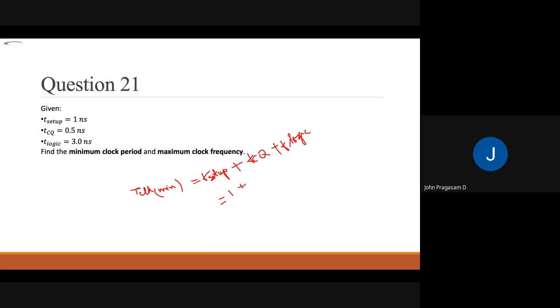In our lab we purchase some HEMT substrates, like aluminum gallium nitride. Yes, we directly purchase the HEMT substrate. Then we deposit or decorate some material, fabricate the contacts, and use it for biosensing or ion sensing, like water sensing, where we can detect any ion present in the water.